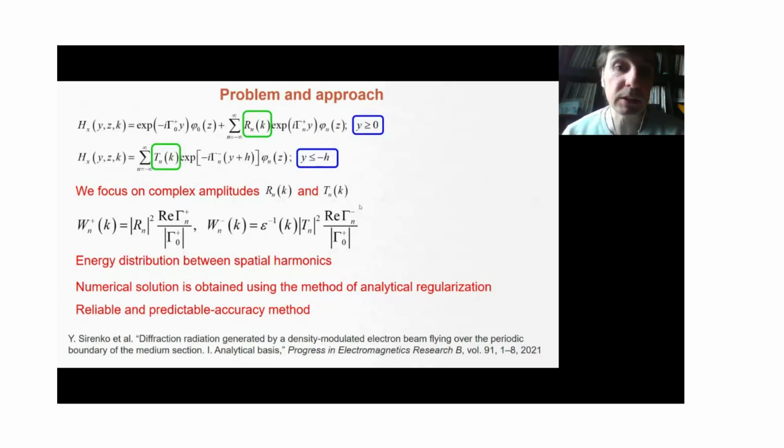And this is of crucial importance for the problems we face, because the structures we study are resonant in nature, and the resonances we face there are of very high quality, with very high Q factors, and they manifest themselves in very narrow frequency bands. So being able to get a solution with high accuracy and high resolution is really important.